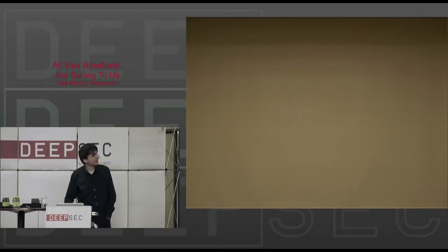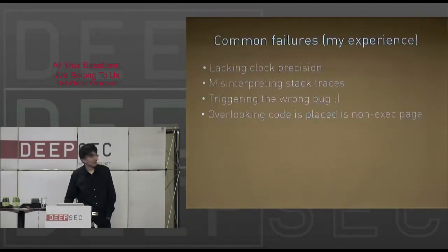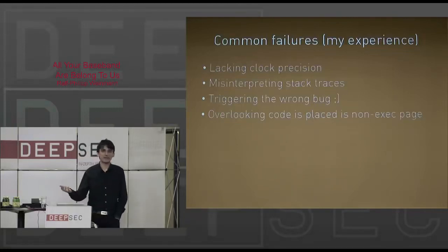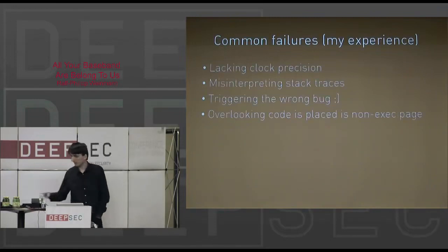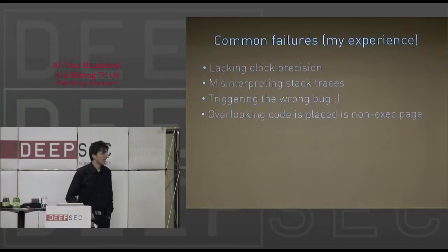Common failures. I flagged clock precision oftentimes because I used the stock clock initially, but also because I had a fuzzy one in this, like an external clock. It's somewhat imprecise still. Even if you tune it, it drifts within the length of this talk, so that an iPhone 4 will not hook onto the base station. But there are better solutions.